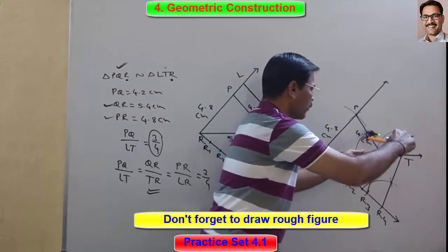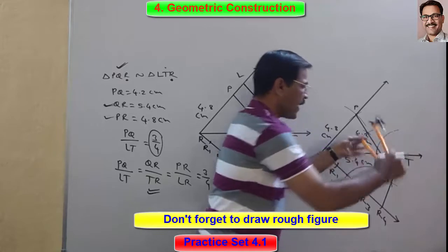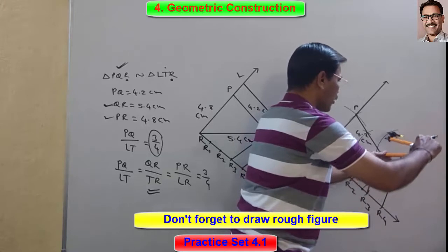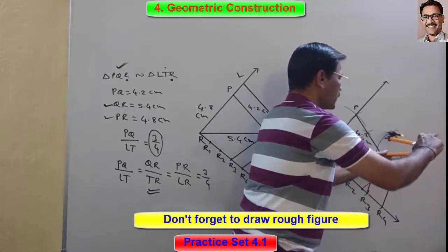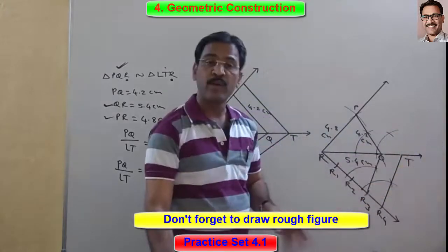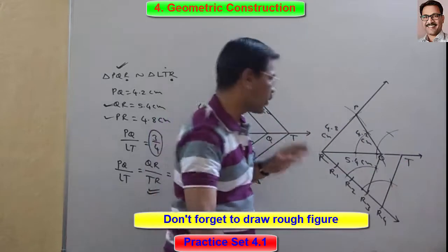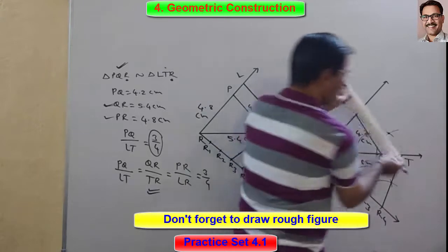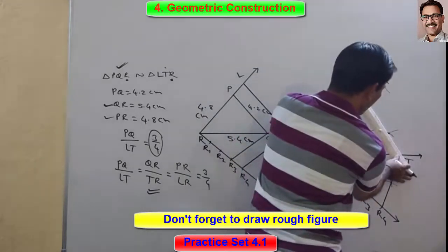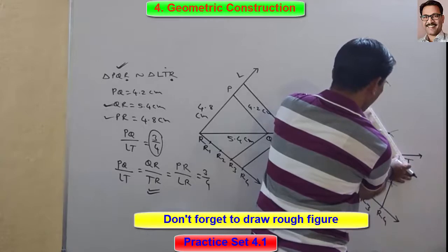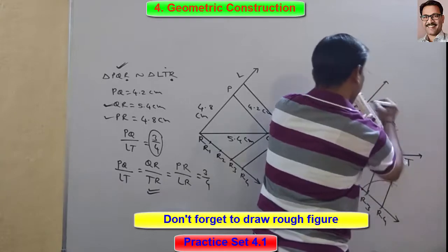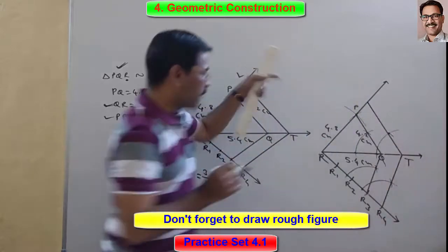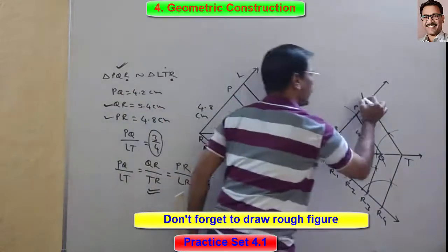Now just try to draw one arc here. Now by this distance, put it on this new point and draw here on this one. This is the point which we need to draw that parallel line. Okay? Look here. Now this point and point P both have to be joined. Means we can get a parallel line here, like this. So that particular point is nothing but point L.